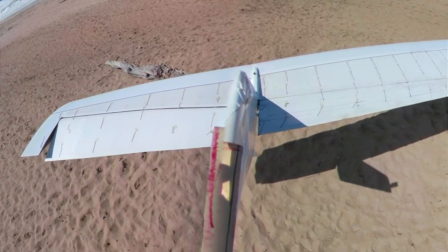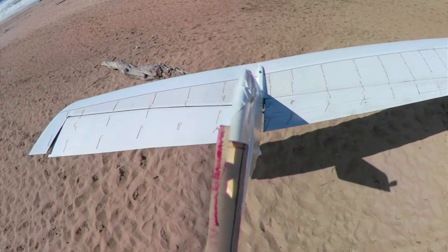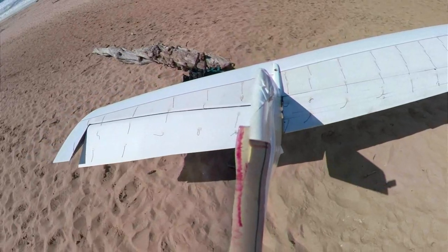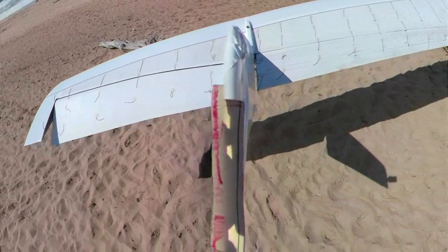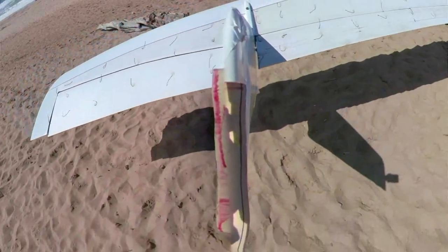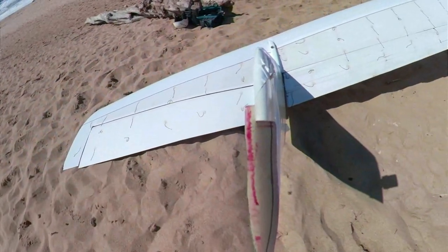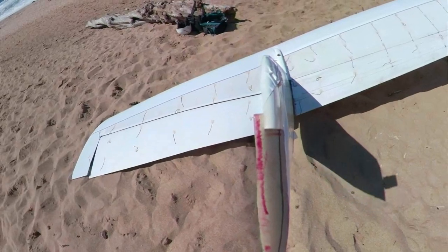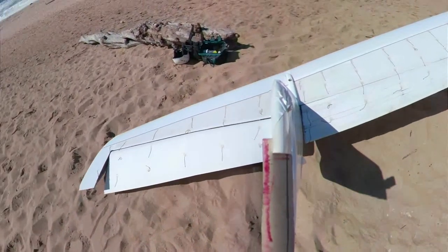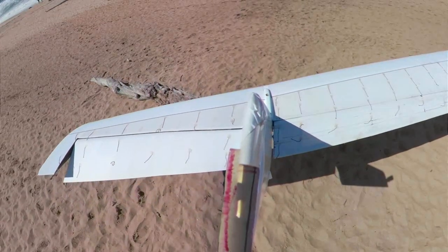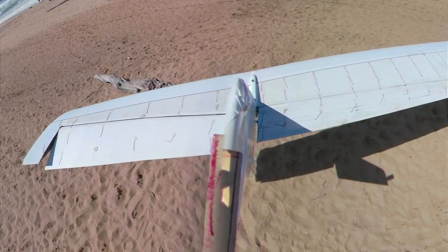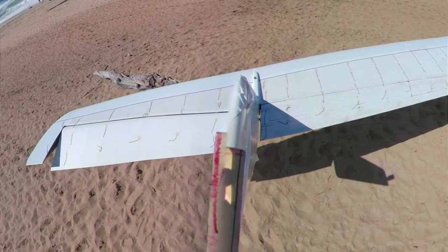So the tip of the elevon is behaving nicely, but inboard is not. And you'll see that unlike when I had the elevon tacked onto the trailing edge, now the inboard elevon is having problems again, just like it did in the past. We're getting span-wise separation and span-wise flow there, which is fascinating to think about. But that's the effect of a potential flow field. You change flow in one area, and if that area is allowed to go span-wise, well, it's just going to drag the other flow with it.